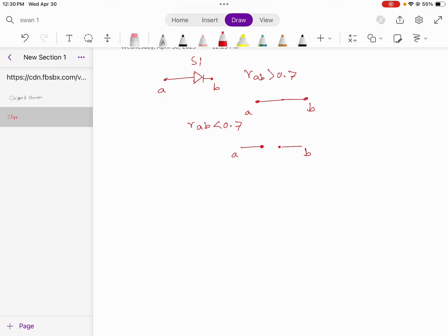So first of all, let's say we have a circuit with an input source, a silicon diode, same as we mentioned earlier, and a resistance. What we want to do is get the output from these two nodes, corresponding to the voltage across the resistance. For the input voltage, let's define a square wave with a voltage magnitude of positive 20 volt and then negative 20 volt.